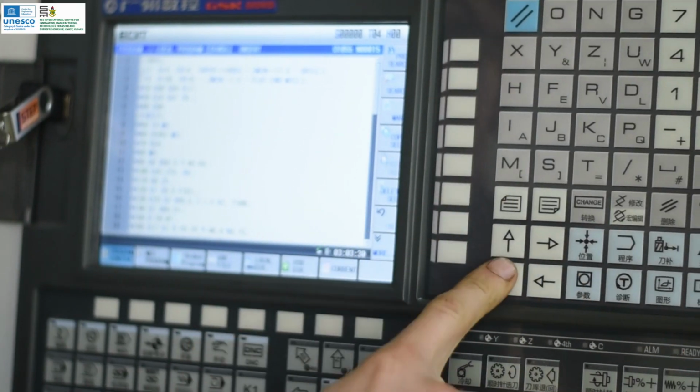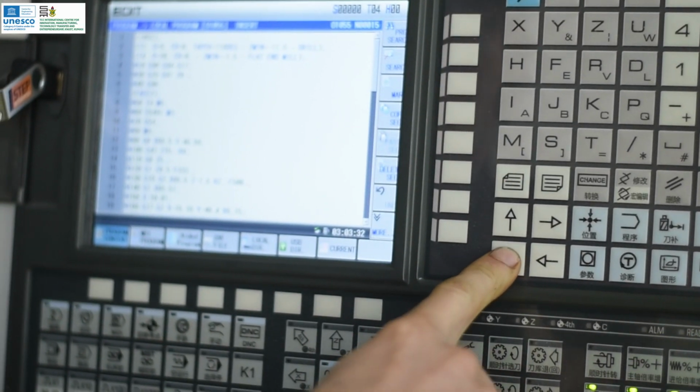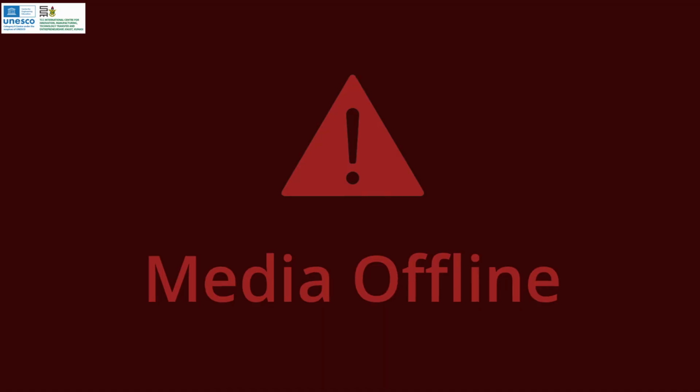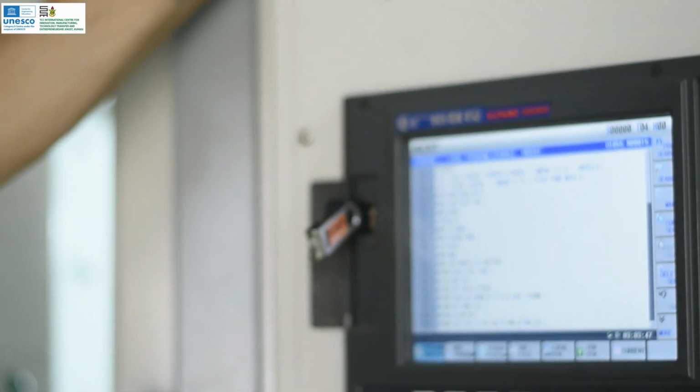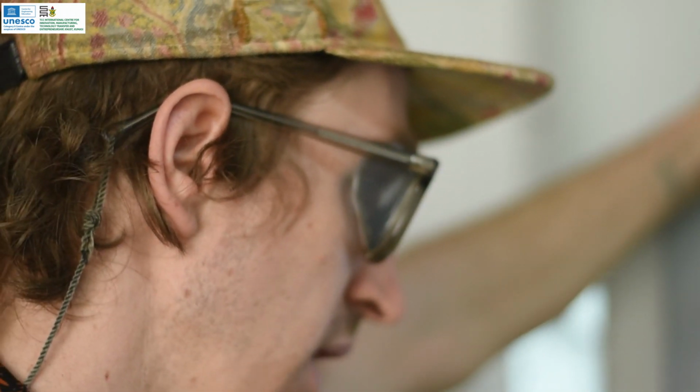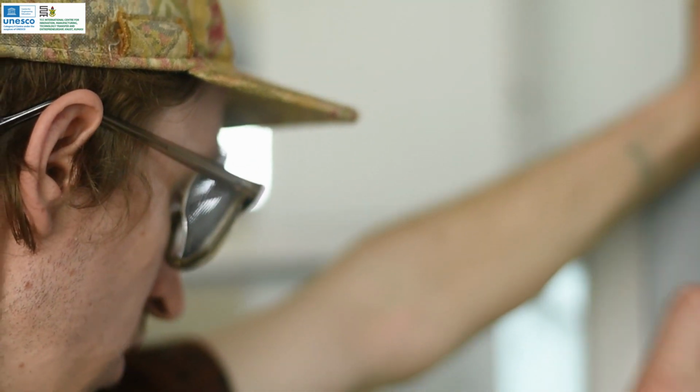Here's that G-code. If we wanted to, rather than editing where we did on the computer, we edited the G20 or G21 and also the M27s, we could be deleting those here in the edit mode. I find it's easier to do it on the computer, a little faster. If you forget to and you don't want to go back to your PC and do that, you can always edit that G-code directly on the machine. Once we've done that, now we're ready to go. We can cut this part.